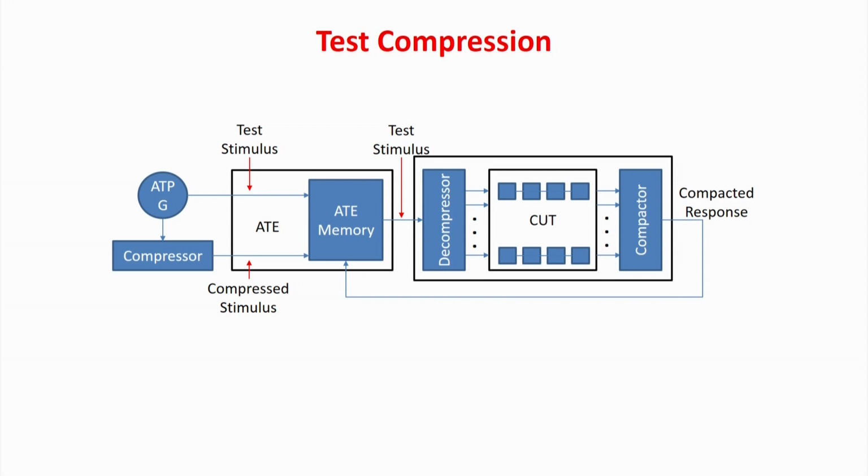I told you, reducing the number of test patterns falls under ATPG generation, and in fact ATPG algorithms are well optimized so that they do not generate redundant test vectors; they generate mostly the minimal number of test patterns required to test all the faults. Again describing pictorially, this is your ATPG algorithm, which will generate the test stimulus, the minimum number of test patterns required to detect the faults, but it will have 0, 1, 0, x, x, x, x. ATPG is not bounding the number of bits.